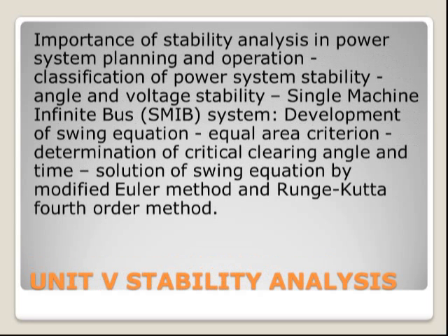In the next slide we have stability analysis. It is essential, and quite useful for power system planning and operation. In order to maintain your power system in a healthy state, power system stability plays a vital role. We have to discuss the classification of power system stability in terms of angle and voltage. In our power system an infinite number of buses are available, but in our analysis we discuss the single machine infinite bus system, and with its help we develop our swing equation.